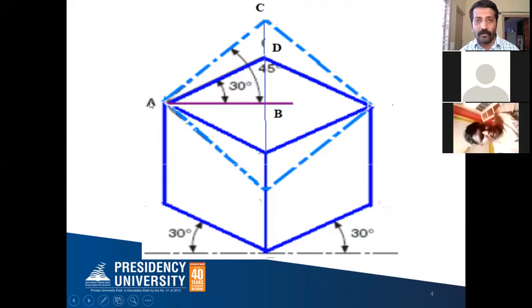That's the same cube I have taken here. The dotted line will give you the actual cube and actual length, and it is 45 degrees. Why? Because the adjacent sides of the actual cube make 90 degrees, half of that if I draw from the diagonal is 45 degrees. It is the actual length. AC is the actual length of your cube edge. And here AD, which is drawn here, is drawn on the 30 degree line. This 30 degree line is the isometric angle where I have to draw the line. AD is the apparent length of this cube edge.